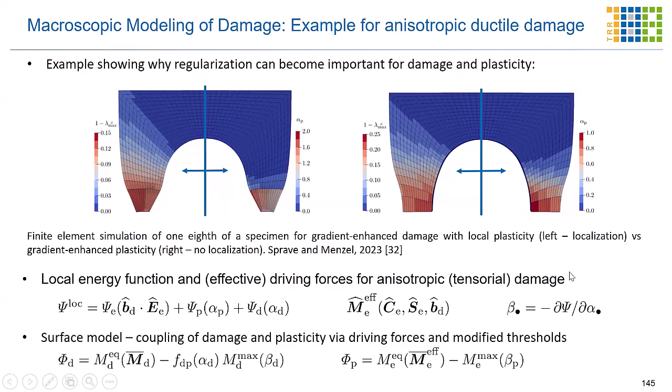And now, another important aspect of this model is related to the tensorial damage variable concept. Before, for the isotropic damage evaluation, a scalar damage variable is introduced. However, in order to include deformation-induced evolution of the anisotropic damage, a damage tensor is needed. Different effective driving forces for both plasticity and damage are derived in a so-called two-surface formulation here. And what is two-surface formulation? Which considers two admissible domains, one related to the plastic flow and one related to the damage evolution.